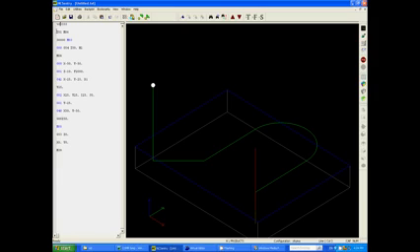Now our next line of code will call up a tool and do a tool change. Now the CNC machine will execute one block at a time, step by step, but a lot of the newer machines actually read ahead so that it buffers the program so it knows what it's going to do next, even though it's just executing one block at a time.